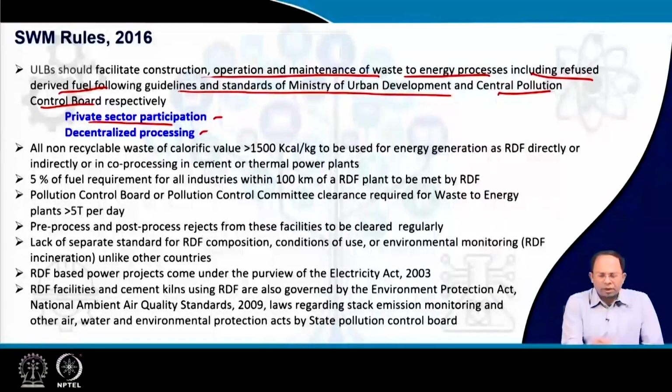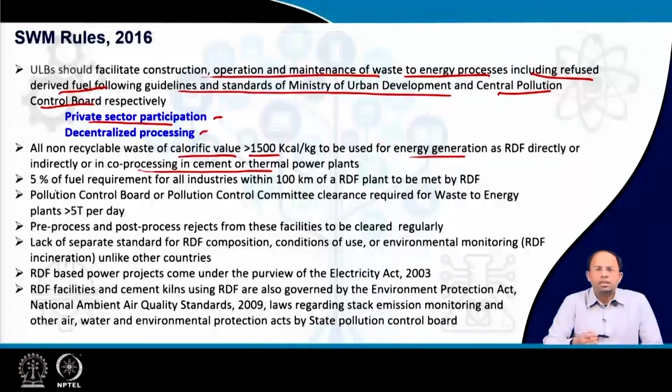The other rule that we have been discussing is that the calorific value has to be greater than 1500 kilocalories per kg for the waste that will be used for energy generation, either directly or indirectly or in co-processing in cement or thermal power plants. Now, how do you facilitate use of RDF in the industry? Because we may produce RDF, but there may be no takers for it. So, to facilitate use of RDF, the government has suggested that 5% of the fuel requirement of all industries within 100 km of an RDF plant has to be met via RDF. That ensures there is a ready market for RDF near urban areas.